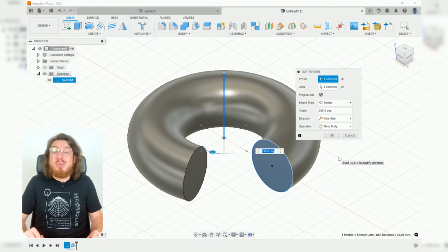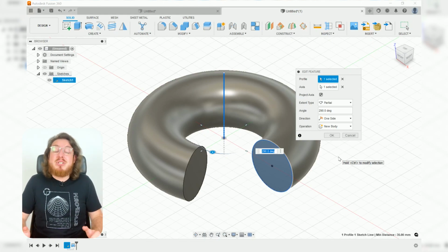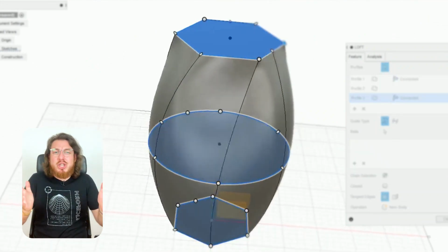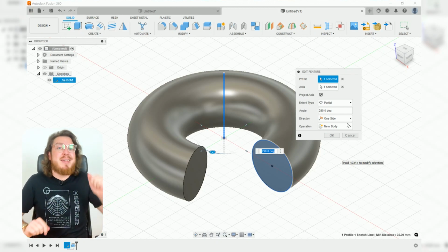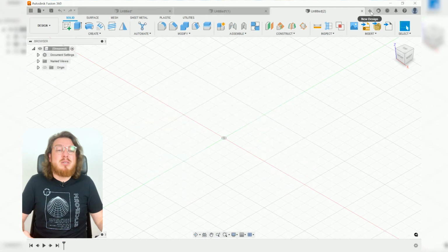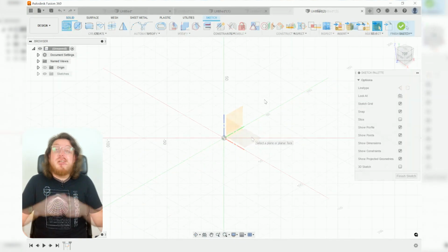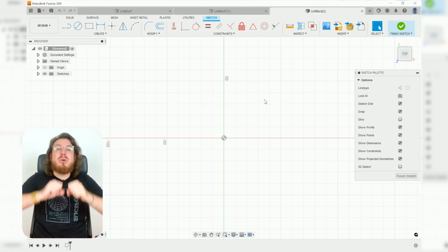The next Create project that we're gonna do is gonna be using the Lofting tool. This allows us to actually merge two different profiles that are laid on top of each other. So they're actually morphing shapes as they rise in the Z dimension. So I'm gonna make a new workspace by, again, clicking the plus symbol. And then I'm gonna be making a new sketch on the top plane. For this project, we're going to be merging between a hexagon all the way up to a circle.